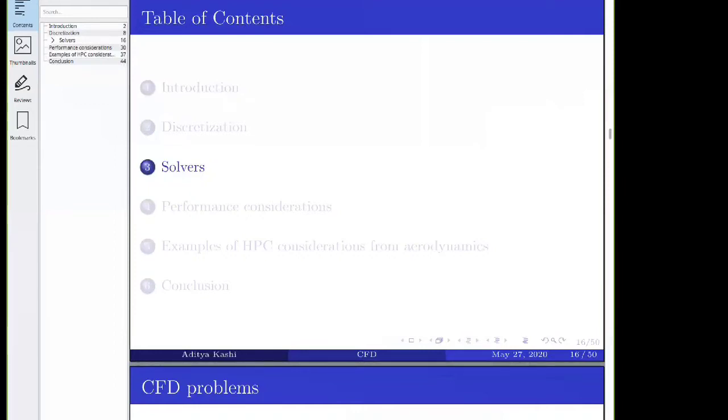Also, if you don't have a hyperbolic equation, I did not go through that part. If you have more of an elliptic problem, or even just for the discretization of the viscous part in the convection diffusion equation, then it's not exactly upwind. We use a central flux plus a correction term. Again, it's kind of similar to the artificial dissipation. Those can be found in some of the references that I have in the slides, and I guess they will be shared at some point.